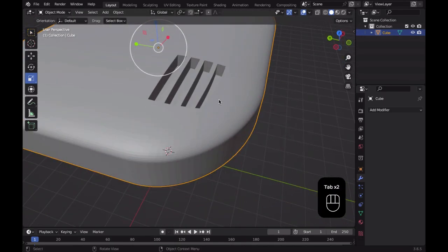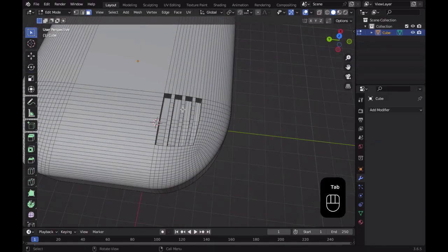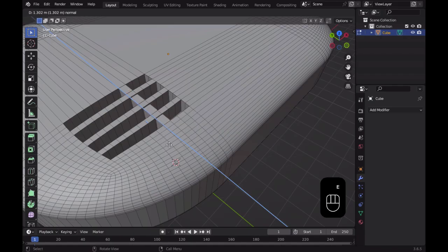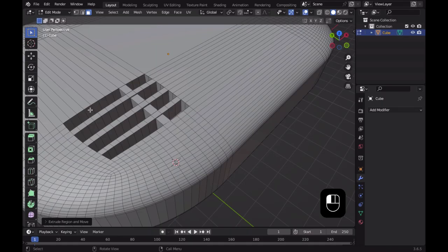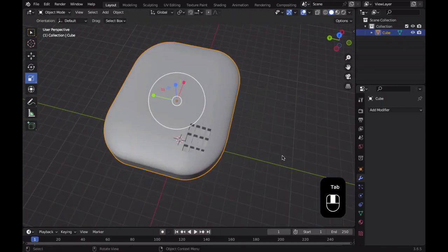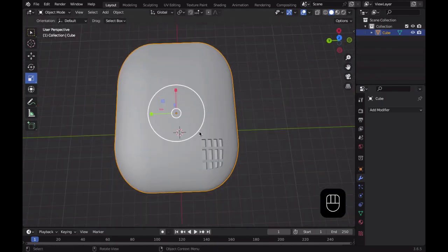And inside we're going to put a couple things. Oh yeah, go out, don't get out of edit mode like me. Anyway, so the vent will be good. So what we're going to do is click like 3 blocks inwards. We're actually just going to click on one side for now. So we're going to press E, and we're going to extrude it outwards, so that it goes through the vent like that. And then on this side, 3 outwards, and we're going to press E, and extrude inwards like that. So just like that, we have got a vent in that sense. It looks good enough, I find.